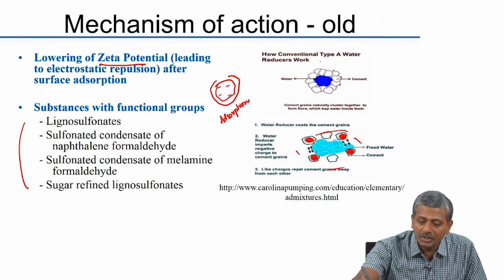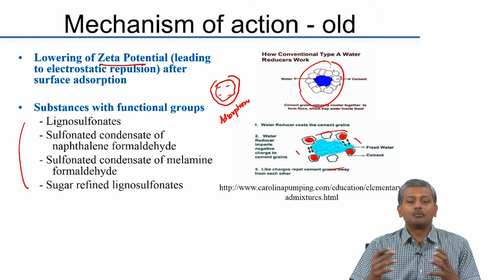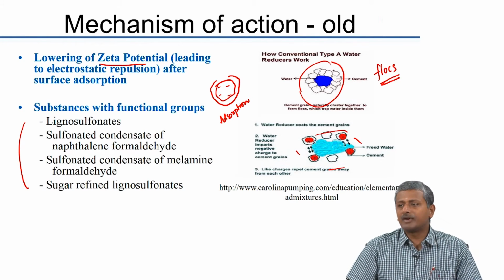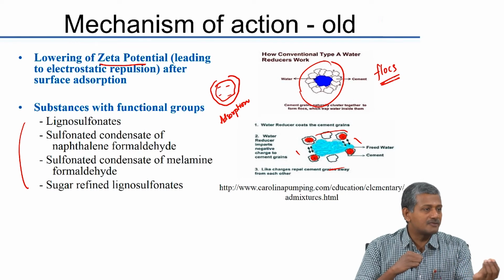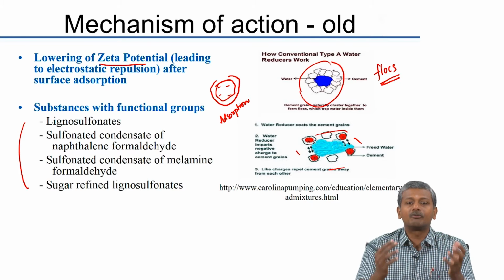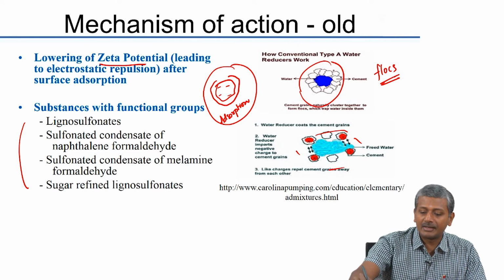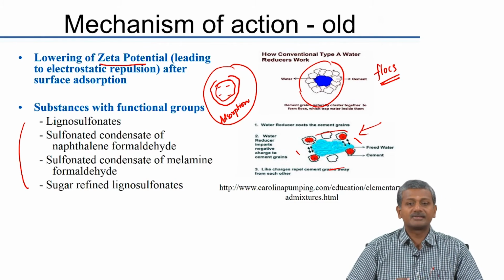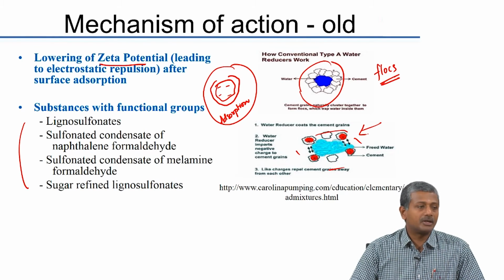Okay? They provide a like charge to all the cement particles, and of course you know from electrostatic principles that like charges will repel. So cement particles end up repelling each other and spread out into the paste. So what happens originally, without the superplasticizer, you have these cement grains which end up forming what we call as flocks. This is common to all fine powders that will be in suspension in water, that they will tend to agglomerate and form flocks, because again they have surface charges here. Okay? So the flocks will trap the water inside and prevent it from moving around freely, which causes workability. So what the adsorption does is that it creates like charges, causes the cement particles to repel each other and causes the water inside to get freed to mingle outside or to flow freely outside. That leads to workability of the paste.